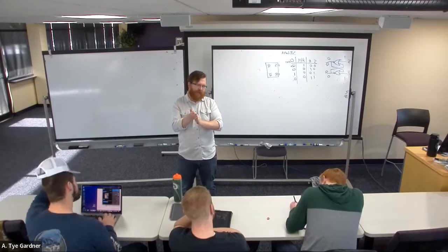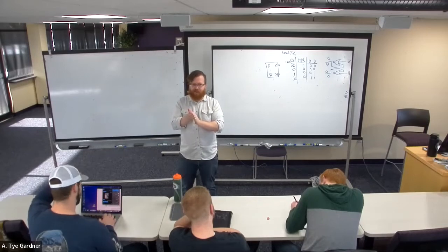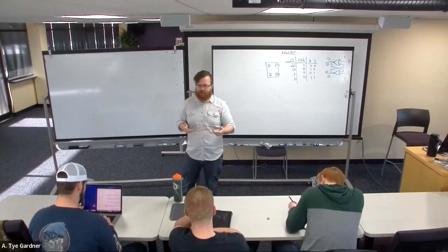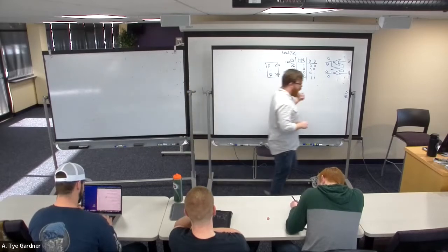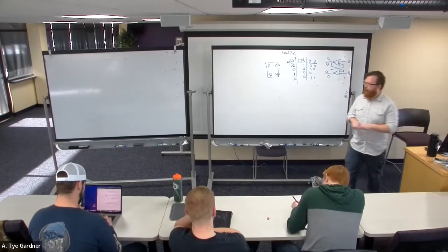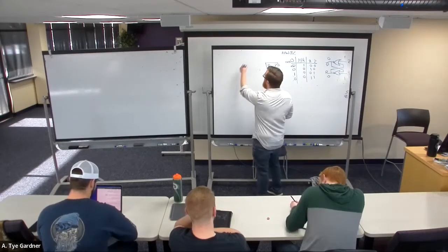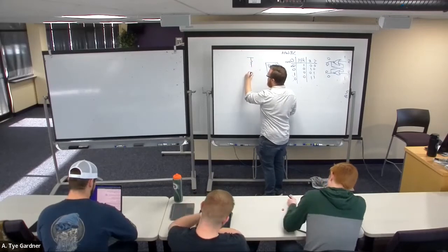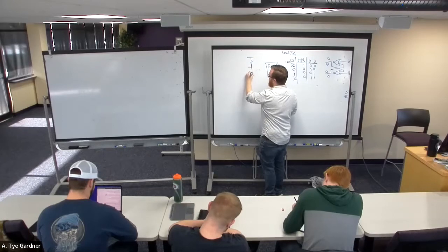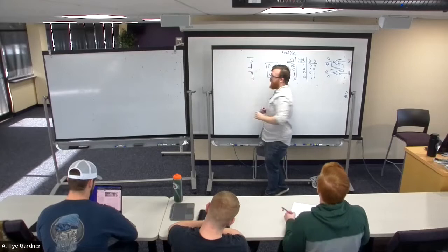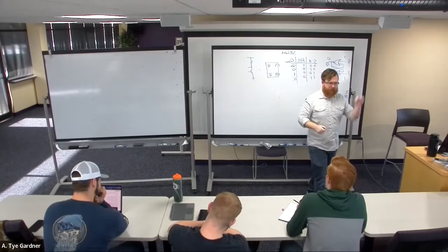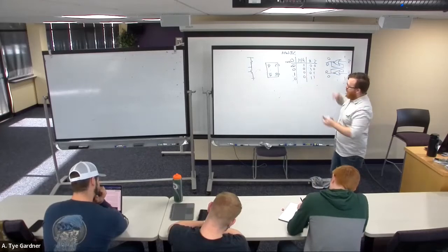So if you're, say, trying to count the number of pushes that you did, each push might be 3 to 7, right? So now you're not sure what you're doing. Turns out the SR latch can help with this problem. It's not perfect, but if I have a switch, and I'm going to draw it like a button just to make it clear. So that's a nice button schematic. And then if you push here, it contacts and completes the wire. It's a button, it goes ting, ting, ting, and it ends up with an issue.